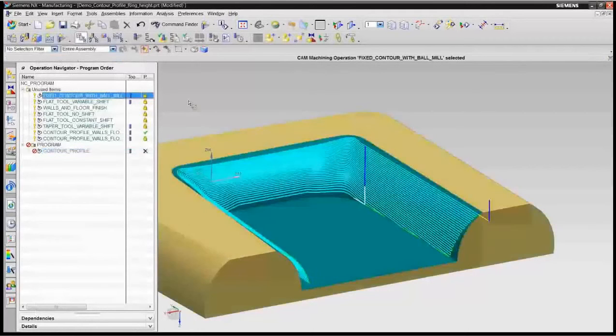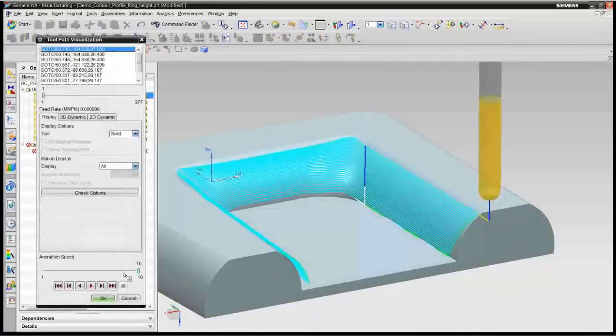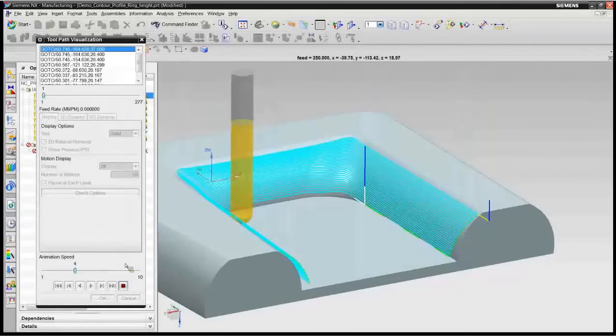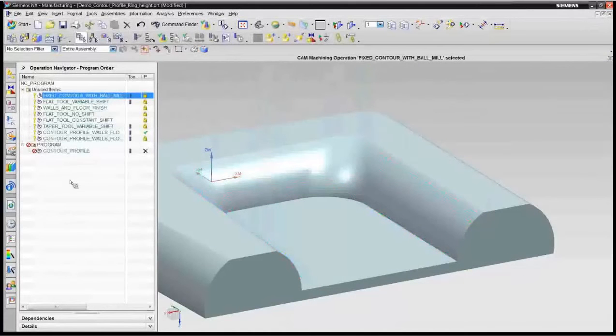and if you come in with just a ball, let me replay this and just show you. The typical tool path that you'd do in the past was you'd machine this something like this with just a ball end mill. The time to do that is actually quite a bit longer. And so what we're going to do is use a contour profile operation.